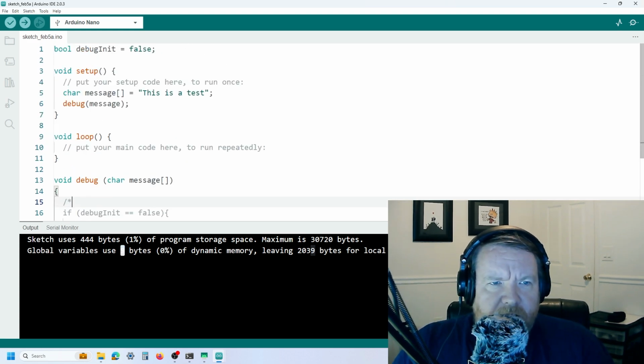So just wanted to make people aware that using the string library in the Arduino, although it might be easy sometimes, may have unexpected limitations, particularly if you have unused variables which are defined as strings. Be aware that that memory is going to be used even if you don't ever use that variable. And I thought it was just something interesting to watch out for.